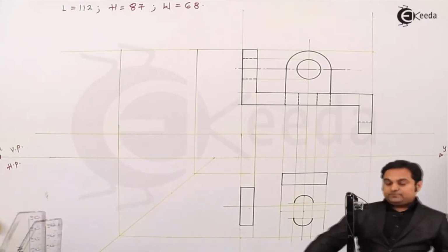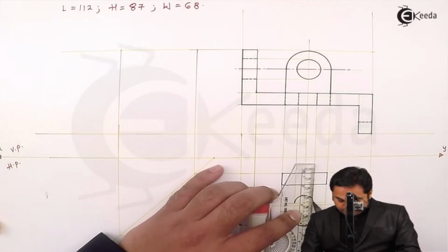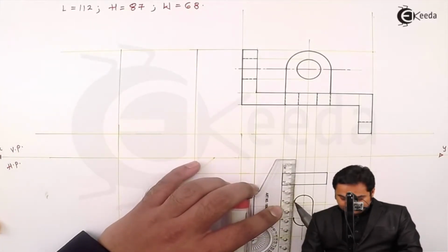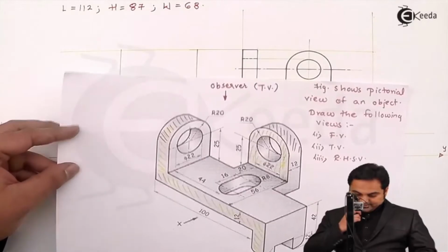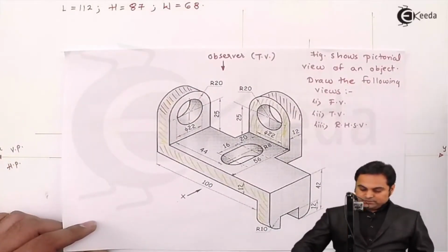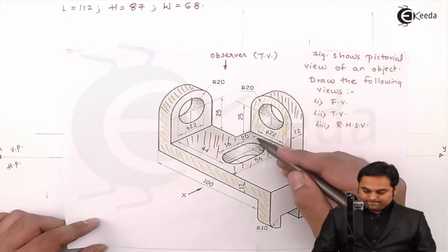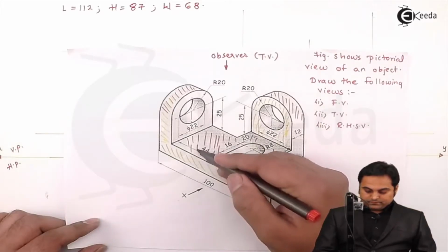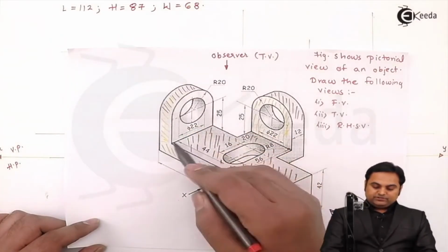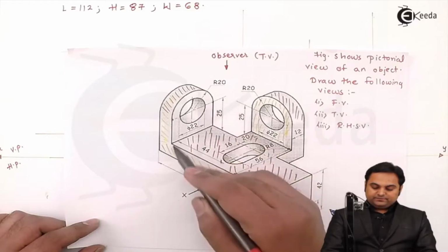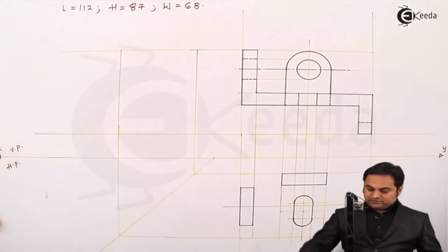Then these semicircles are being joined with the help of a dark line. So this portion is visible from the top. Next, after that, looking from top, this surface is visible. So here, this semicircle has the same diameter and this width is the same. So it will go on continuing. So I will just project that semicircle.